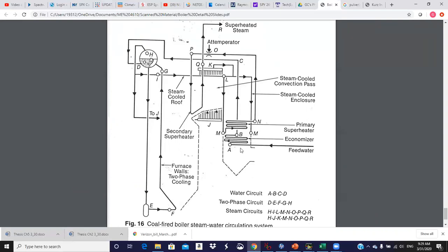But anyway, so A, feed water comes in on the feed water line. So that's where it enters the economizer, just a tubular heat exchanger, has hot flue gases. Actually, they're fairly cool flue gases, but it's still probably 800 degrees, something like that, which is pretty warm to me, flowing across it. So then feed water enters at A, comes out at B, and then that's back in